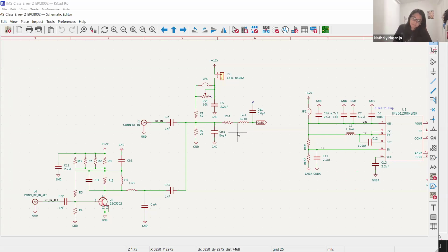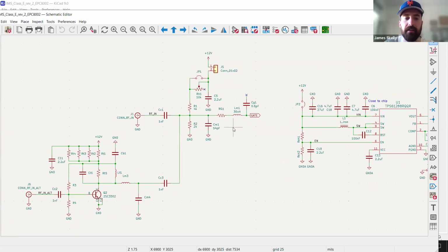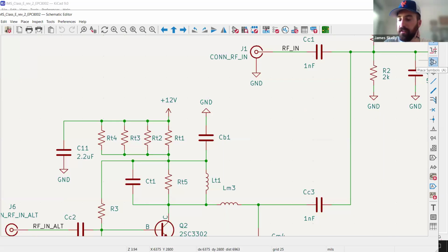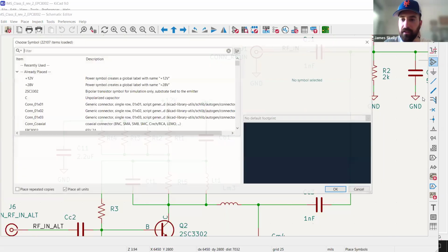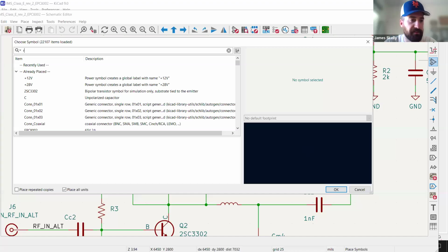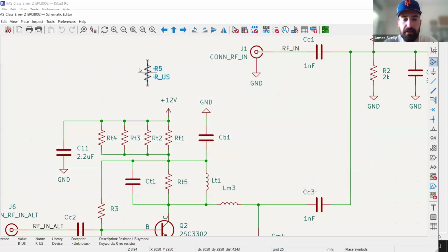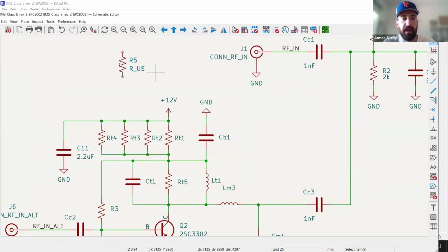And so when you do draw the schematic, which is the first thing that you do, you physically go in. Let me put a new part. I'm just going to place symbols. You can see that I can pick a symbol. I'll just pick a resistor, very basic. And when I place this resistor, because this is just a symbol, you'll notice that at the bottom of the screen it says footprint unknown, because there is no footprint until I assign a footprint.